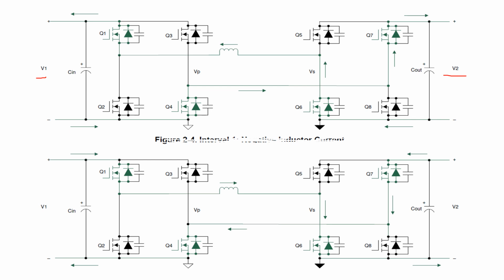In a single phase dual active bridge, the primary and the secondary bridge are controlled simultaneously. So all switches operate at 50% duty cycle. That simply means that the diagonal switches turn on or off together so that the output of each bridge is a square wave. The switching sequence of the converter will be explained in this video.